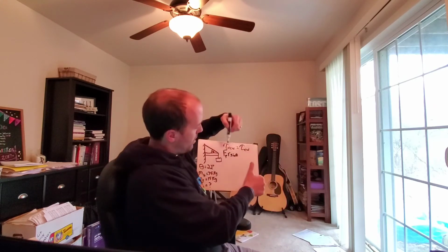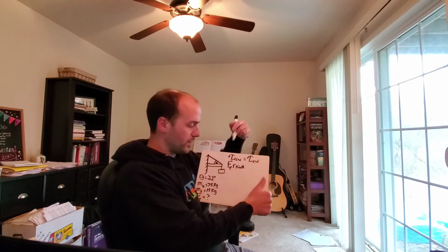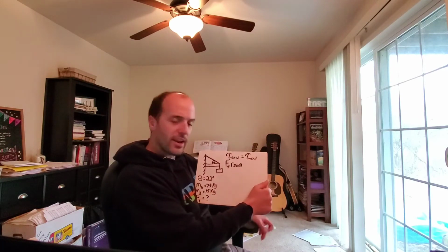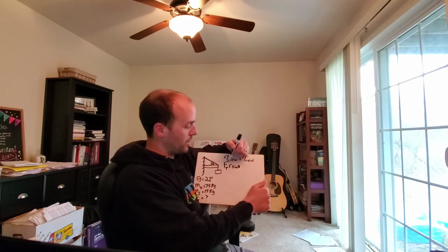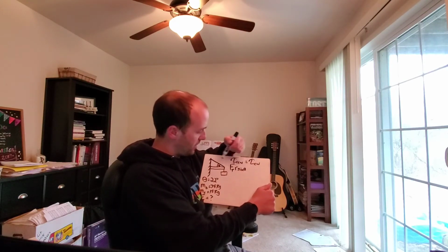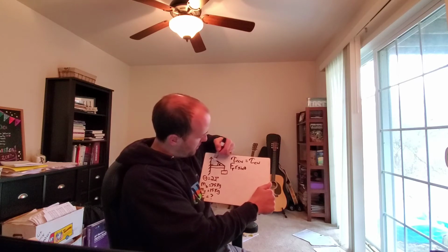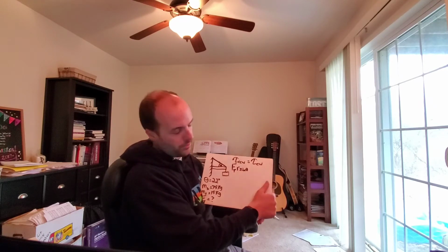All right, so torque equals force times the moment arm times sine theta. I already established that this is our force of tension. That way I don't need to waste a spot there, but that is our tension force that we're going to end up solving for. Here's our moment arm, and here's our sine, and there's our theta. This theta is going to be important because if my tension's up this way, here's my force. My moment arm is this way. That angle has to go there.